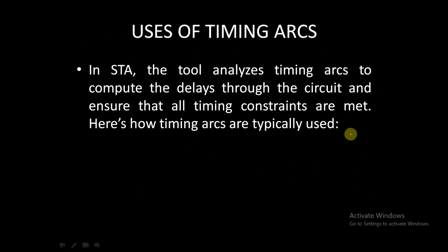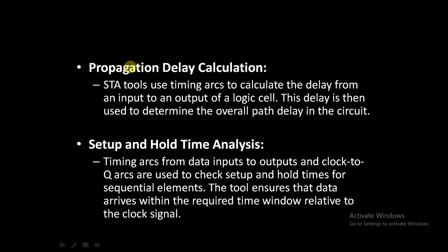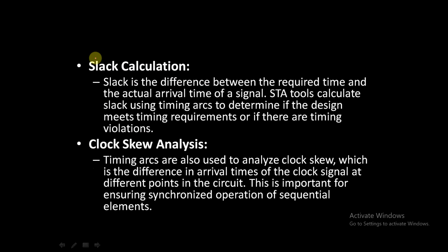The use of these timing arcs is that the tool analyzes the timing arcs to compute the delays through the circuit and ensure that all timing constraints are met. The propagation delay calculation will be performed by the tool, and the setup time and hold time analysis will be performed on slack calculation.